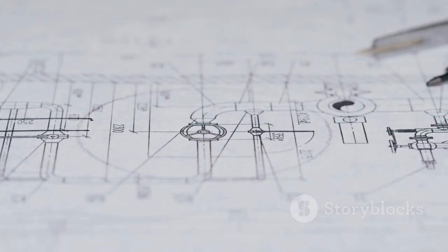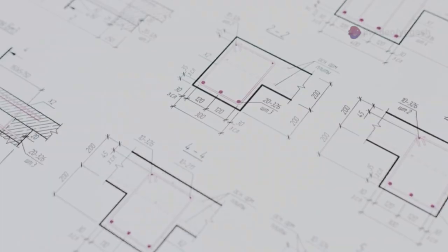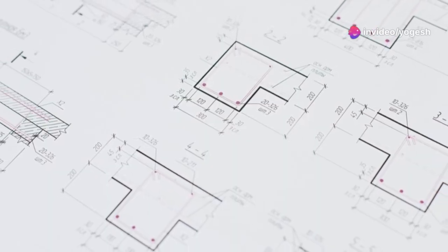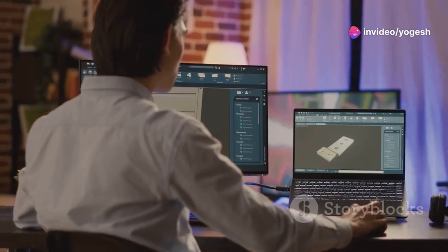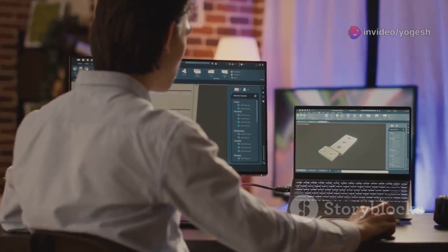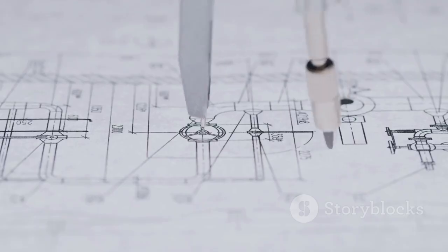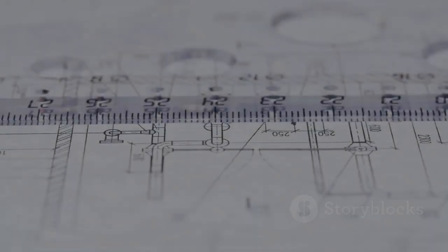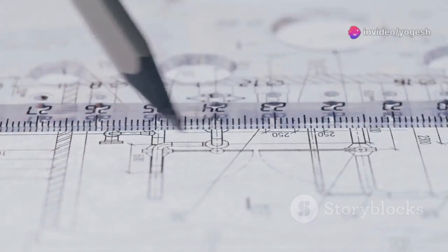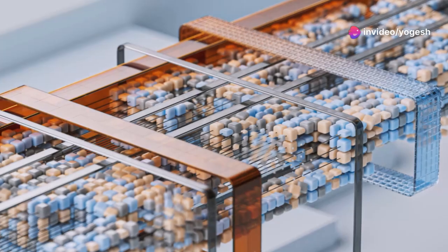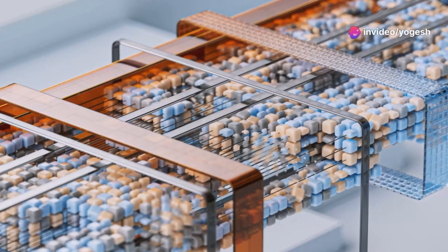Construction lines are your invisible helpers. Thin, light lines used for layout and geometry. In CAD, put them on a non-printing layer so they don't appear in the final drawing. They're for your eyes only, never for the machinist. Use as many as you need, but keep your final drawing clean. Organized construction lines make complex drawings much easier to build.